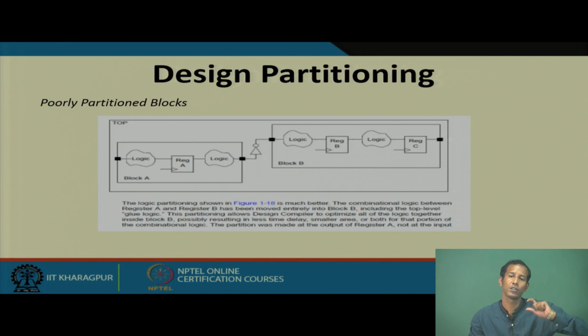Because if I place one cell of the FFT in one corner and the other cell of the FFT in another corner, the net delay will become too long and it will unnecessarily increase the cycle time or the critical path. So, whenever we place the design, we have to remember, or the tools have to remember, or we have to tell the tool, to place the design closer where there is connectivity or interdependent connection between two sub blocks or two blocks.